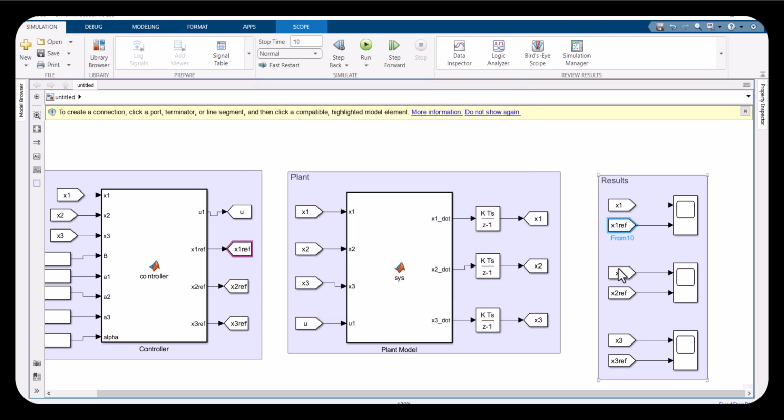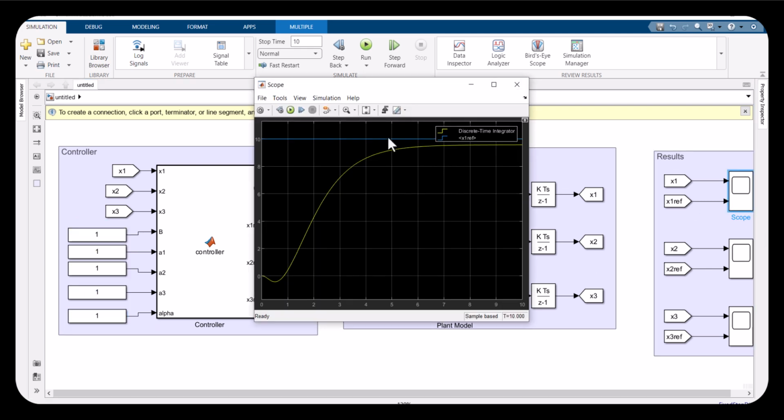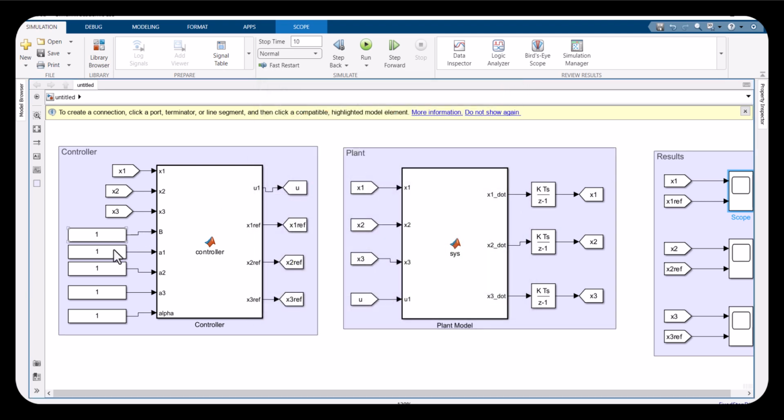You give the input for what you want this state to be, you design a controller, you put these equations in and compute, check the results, and compare them with the reference values. Here I would add a point that the values of these gains make a huge difference. With the values of 1111, it took about 7 to 8 seconds to reach a value near 10. So we can use optimization algorithms and different techniques to compute the best values of these gains, sorry.